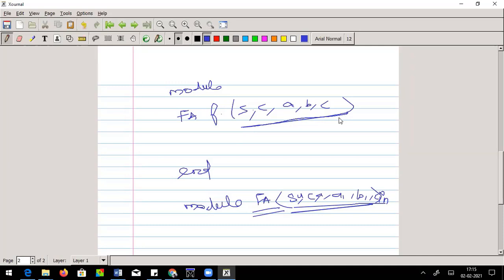If you are not following the order, a wrong signal would be assigned to a wrong value which is being computed here. So you need to make sure. This is called module instantiation by order. Otherwise, by name you can do it.